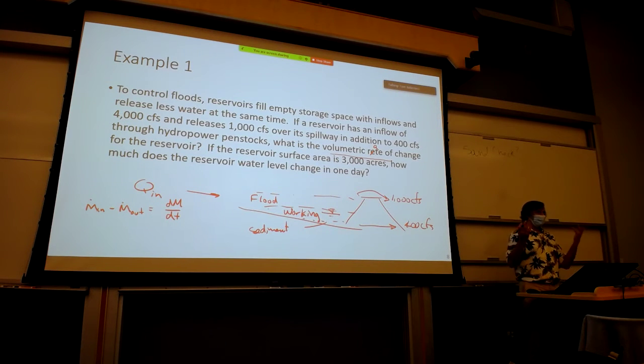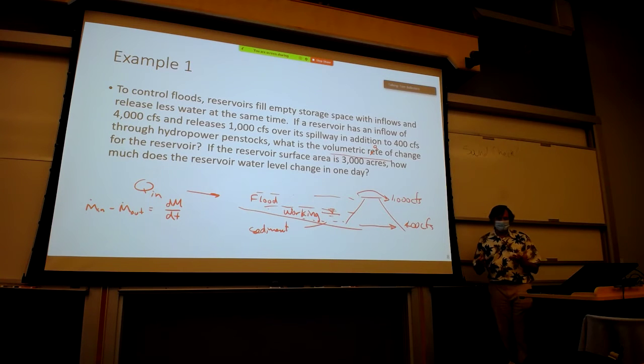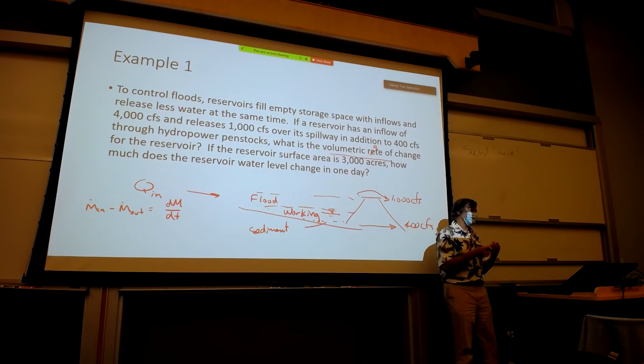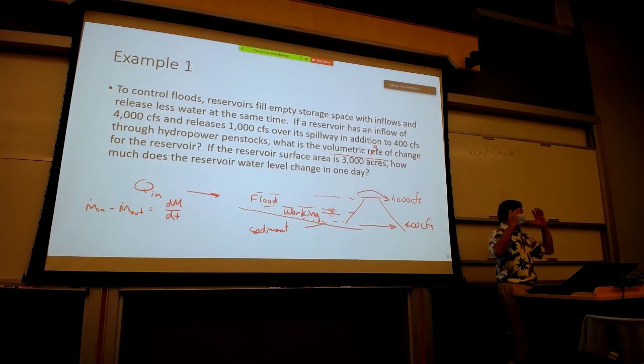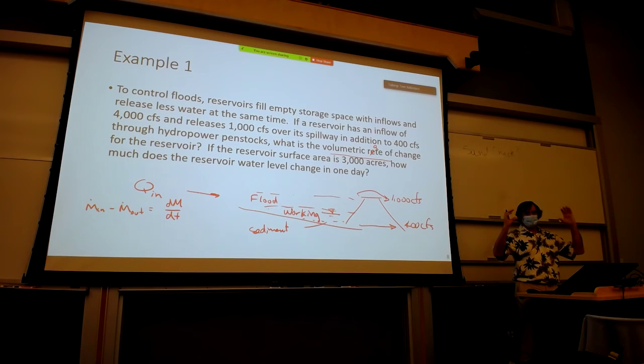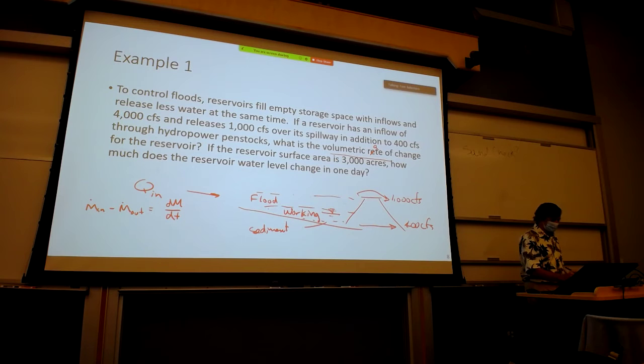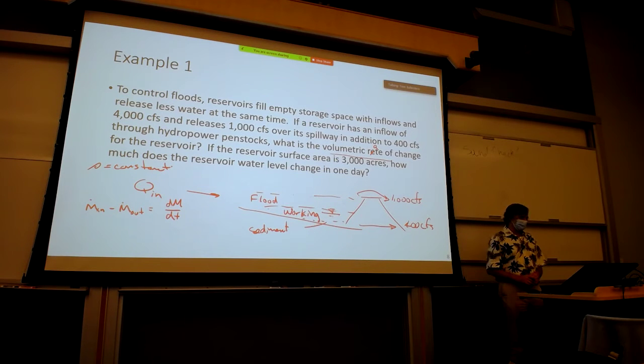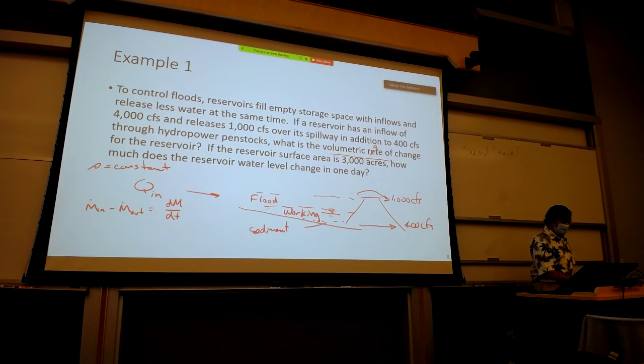If we have a constant density fluid, and so again, with liquids, we typically assume for most of the pressures we work at in engineered systems that the liquid is incompressible, water, for example. And so when we say an incompressible fluid, we're saying basically in this system, the density is going to be a constant. And we can factor out the density from each of these terms.